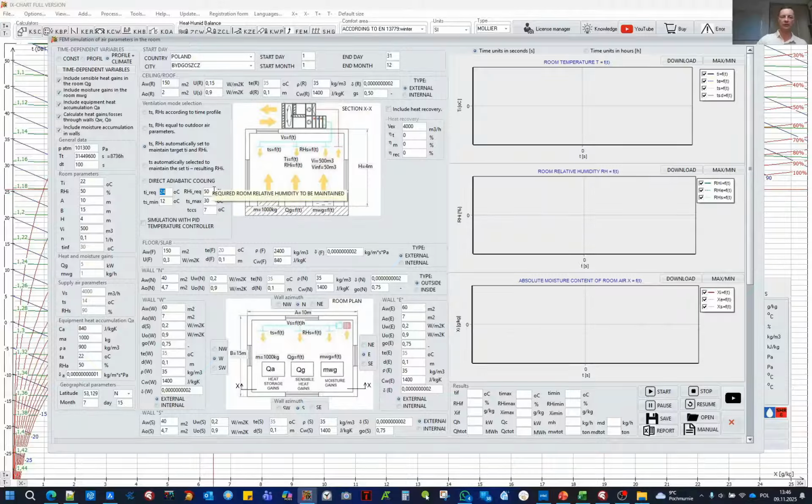what we want to achieve in the room, what temperature and humidity we want to control, additionally defining the parameters that the system can achieve, the lowest airflow parameters and the maximum airflow parameters. So here for cooling, here for heating, and what will be the minimum temperature of the cooler wall that the system can assume in calculations, depending of course on the type of refrigerant. Will it be direct evaporation? Will it be a chilled water unit?